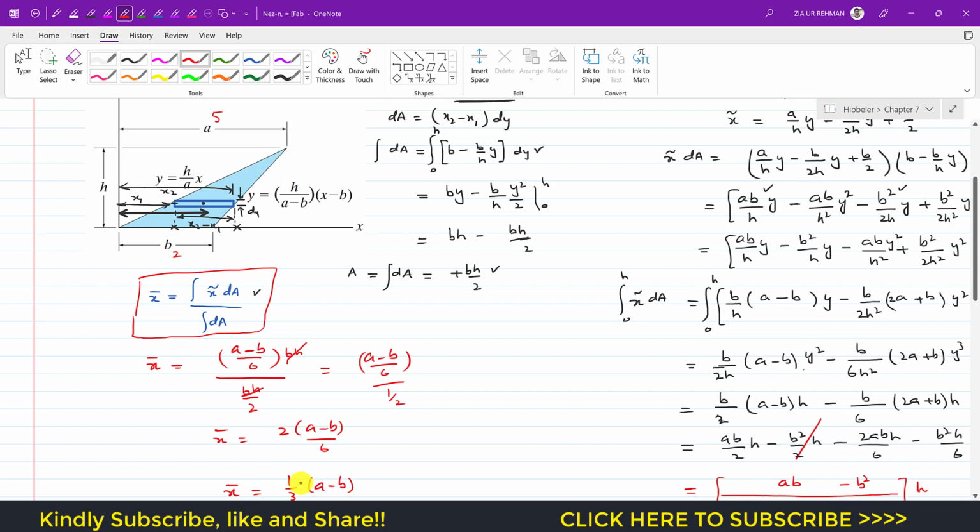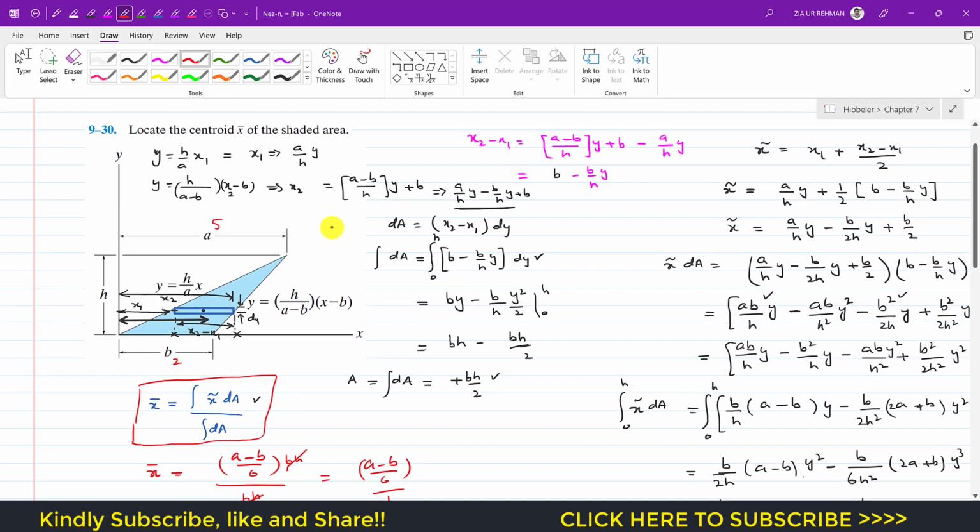This is the universal formula now. So this is 1 divided by 3 into a minus b. So a is 5, minus b is 2, 5 minus 2 is 3, and 3 divided by 3 is 1. So this means that x bar will be located at a distance of 1 unit from the y-axis.